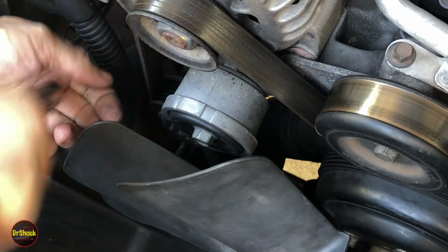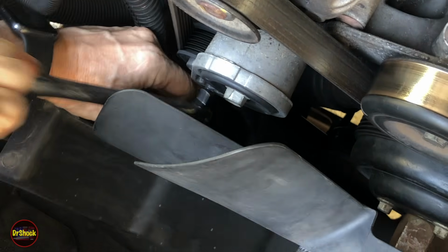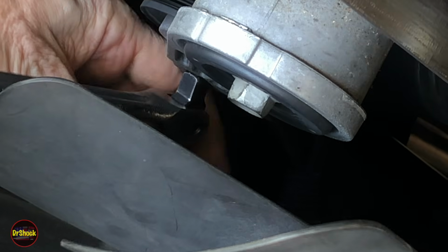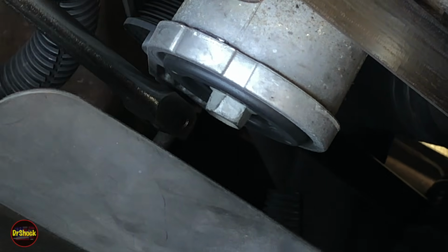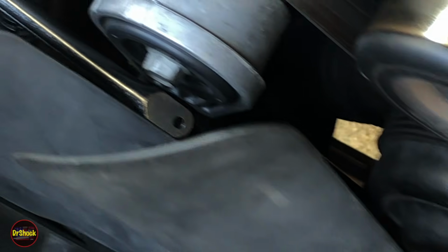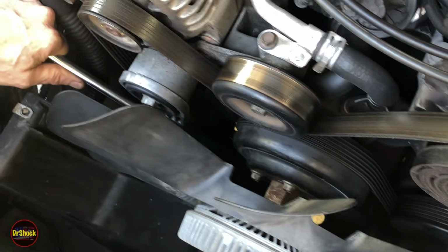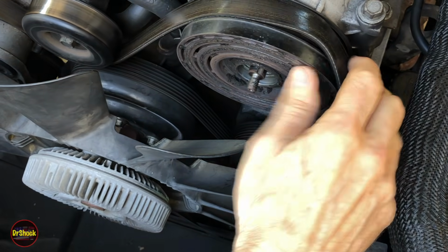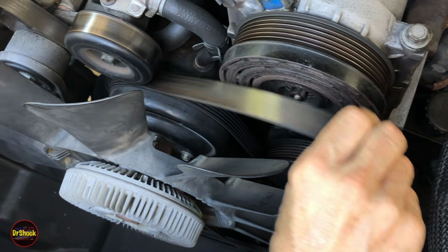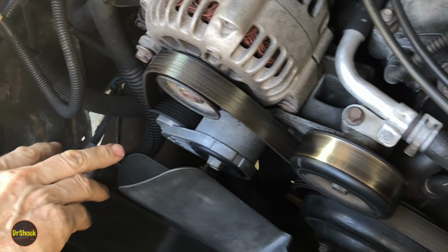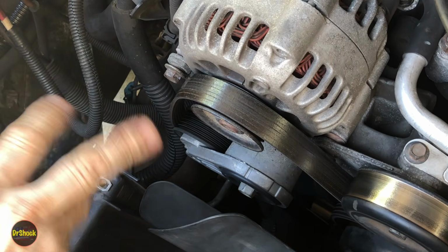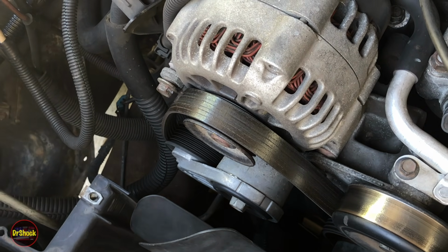This is the tensioner for the belt right here. And then at the bottom is going to be an insert for a square drive tool like this 3/8 breaker bar. Pull that down. Never get your finger underneath the belt in case the tool slips. Just gently let that guy down. Let that back up. The shape and the design of the tensioner will be a little different on the 6.5 liter and the 7.4 liter, and I think also on the 4.3 liter.